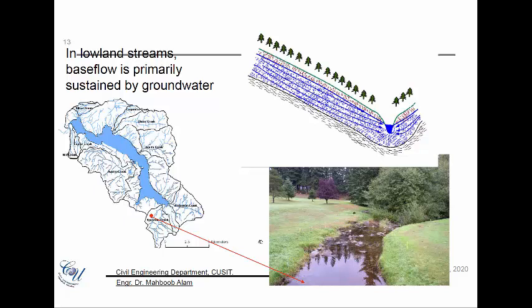So as we said, we have a groundwater component, and when there are favorable conditions, that groundwater would contribute to the stream flow. So the water that is flowing in this river, for example, is contributed heavily by the groundwater, and this is typical of catchments which are in lowland or plain areas.